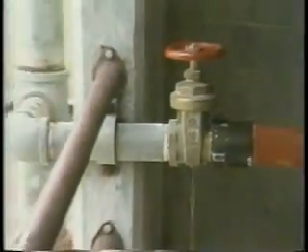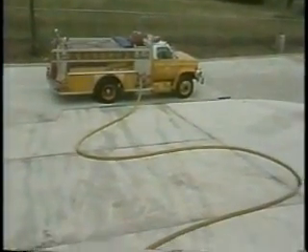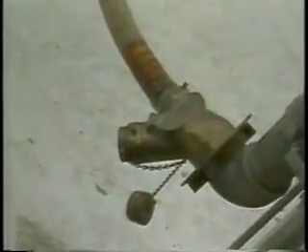Taps are located at each level for connection of firefighting equipment, or cabinets may be provided complete with fire hose. Many departments prefer to use heavier duty fire hose rather than the hose stored in many of these installations. Pumper connections to standpipes permit the fire department to provide adequate pressure for most firefighting situations. If a pumper is committed to a standpipe system, that should be its total commitment.